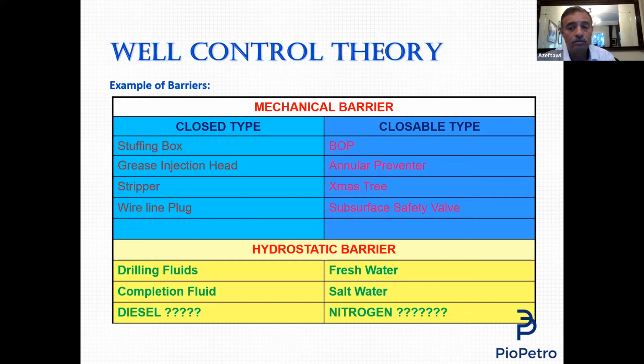No, I cannot. Why? I have two concerns. Number one, it is flammable, so safety-wise, I cannot. Number two, normally it is lightweight. It does not create enough hydrostatic head to kill the well or to use it as a barrier.